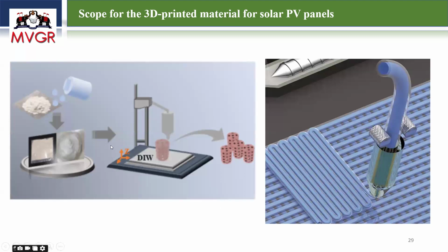So this is the fused deposition modeling technique. If you make the shape-stabilized material, we can pass that material into any extruder. If you pass it through an extruder, a wire structure will be formed, and that can be easily printable. Similar to polymers, how do you print using polymers? Using the fused deposition modeling technique, the FDM model. In the same way, you can make the leak-proof material pass into that wire, and it can be easily printed.